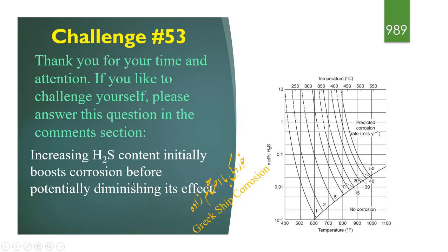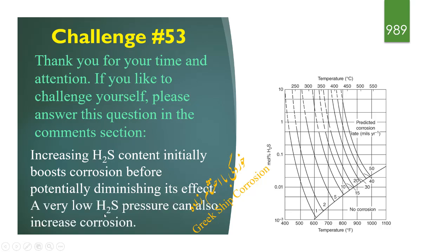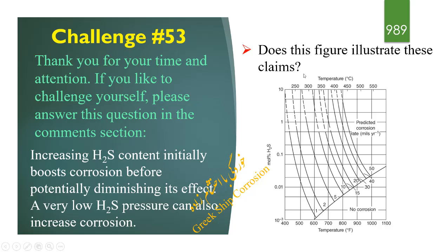Increasing H2S content initially boosts corrosion before potentially diminishing its effect. A very low H2S pressure can also increase corrosion. Thus, this figure illustrates these claims.